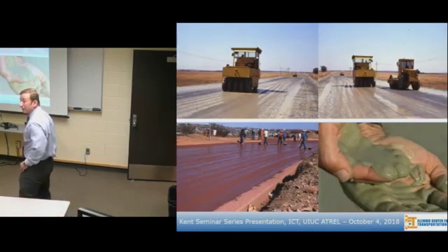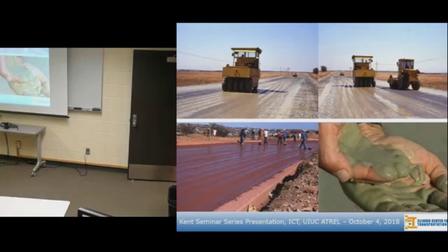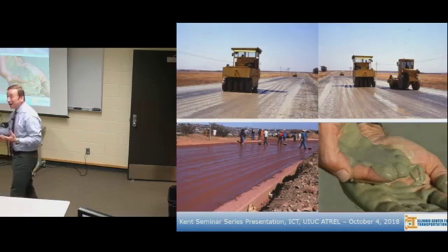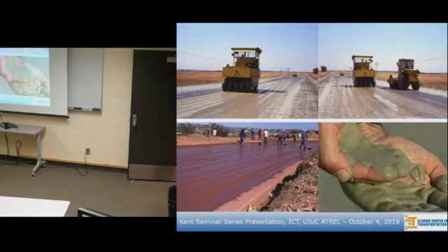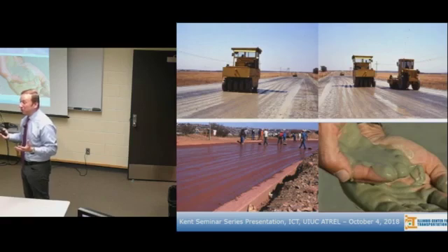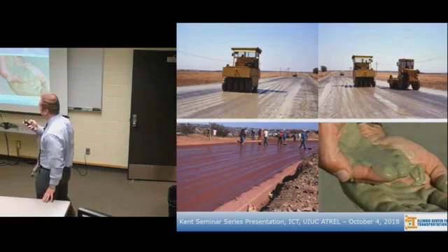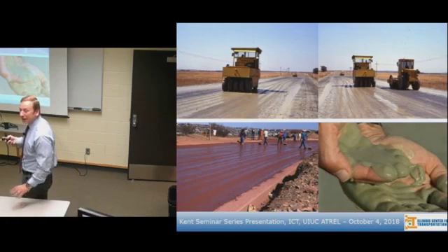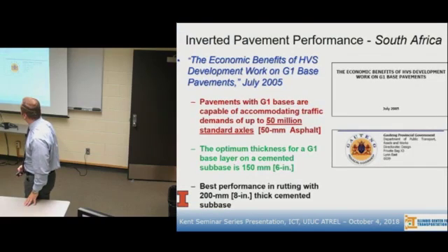All right, I think that's the end of it. It may sound to you like a cumbersome and long process, but the clever way is actually keeping fines in place to achieve the compaction densities in the first phase. In the second phase, we don't need those anymore. Let's get rid of them by slushing, and that's exactly how you get the fines out. It's a beautiful process, a really nice way of getting a dry layer that is almost like a bound layer of concrete, which is what you see from the trenches.